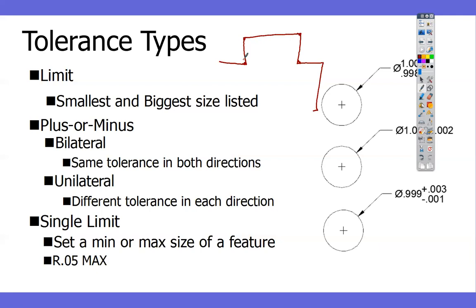So that was just part of my process for designing it. Okay? So if you get to do something where you're going to be programming a plasma or laser or something, keep that in mind. Just little, like a 1/16 of an inch. You can't really tell what that is on the finished product, especially if it's going to be bent up on a flange or something, or even like a 0.03, like a 30-second radius. That's super tiny, just enough that it's not going to dead stop. And that would be the definition for the single limit.